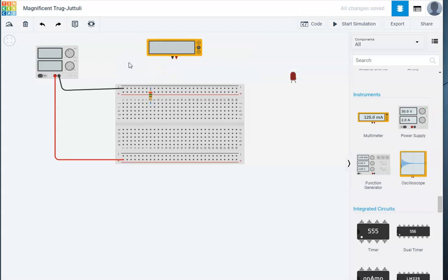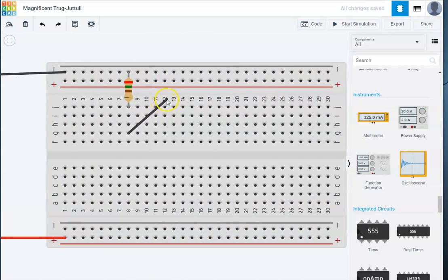Like that. It just so happens that when I placed it here, the other end is now in these little strips. Okay, this little strip of 5. So if I want to connect the resistor to something else, I just need to plug this something else into one of these 5 holes. Now that something else could be directly going to another component, or could even just be a wire. If you wanted to use a wire, I can zoom in.